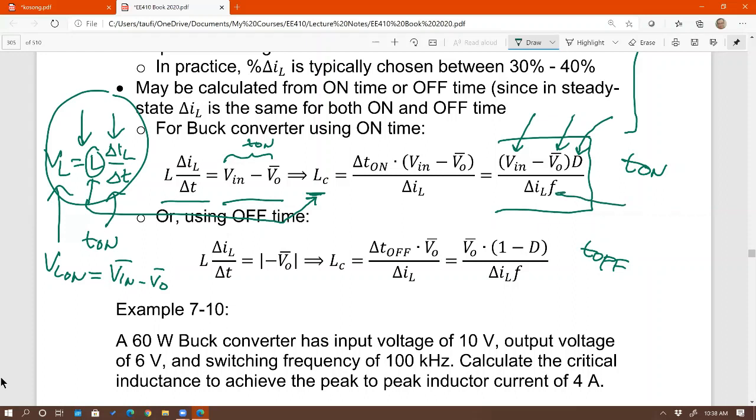How about frequency? That's another thing that you have to pick. If it's not given by the customers, then you have to pick. So select a switching frequency, let's say 500 kilohertz. Sometimes you don't have any choice. Sometimes it is determined by a controller. The controller will say fixed switching frequency, so use that frequency. If the controller data sheet states that it's a variable frequency from one frequency to another frequency, then go ahead and pick one frequency for now. You can always optimize later.